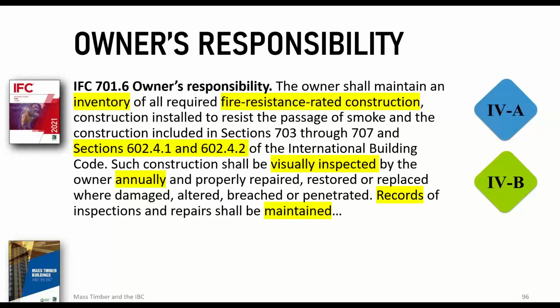I wish it was for all buildings, not just mass timber buildings, because when I was a fire marshal in Baltimore City, we got into some high rises, and it was amazing the changes that building management made. We had one that we hadn't been in for years. It was an older high rise that wasn't required to have any fire permits at the time. And we got in there and found that they had taken the building fire pump and replaced it with a marine boat pump. I guess the old pump went bad, and they just found another pump, and it has nothing to do with mass timber.